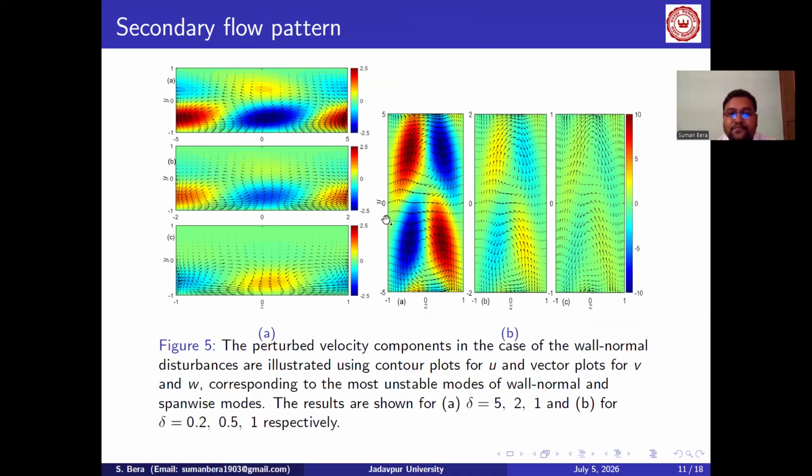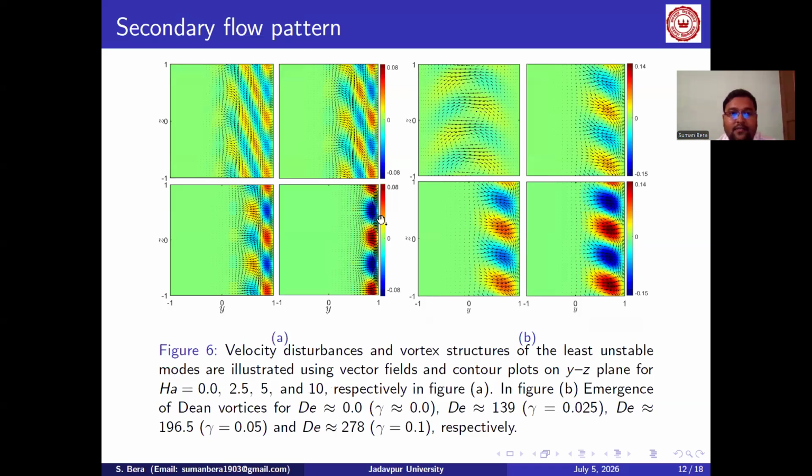which denote mixing or instability. For high and low aspect ratios due to rotation, the vortex strengths are high, denoted by the vector length and the color, whereas the magnetic field has a stabilizing effect, and the vortex layer and the strain decrease with Hartmann number, whereas the counter-rotating Dean vortices due to curvature shift with increase of the Dean number, and the strength also increases as shown by the color.